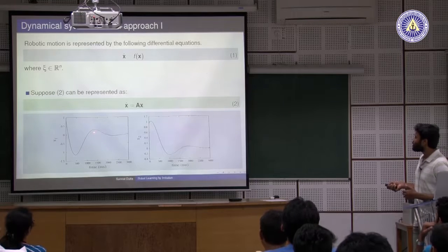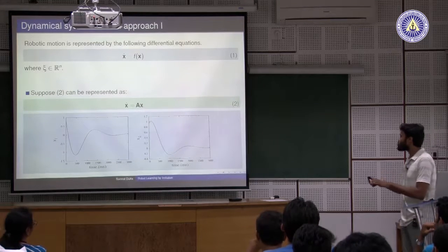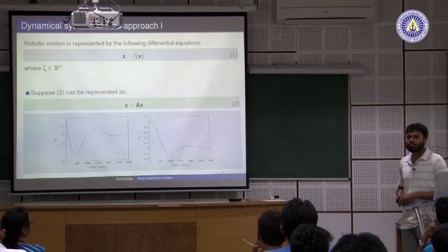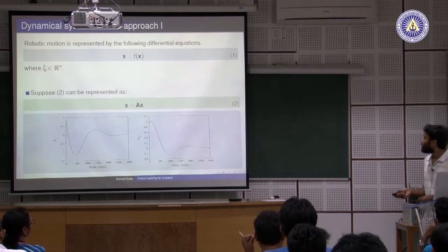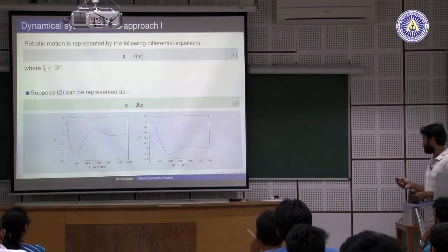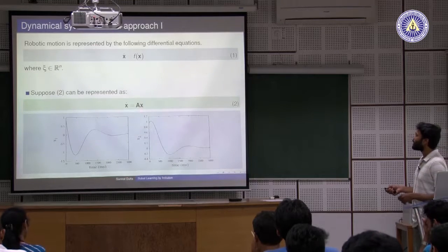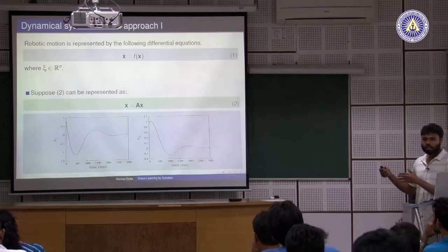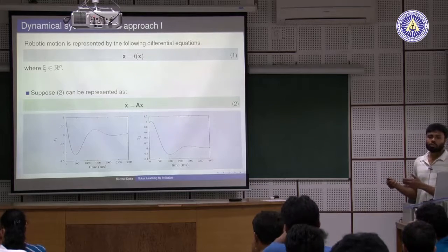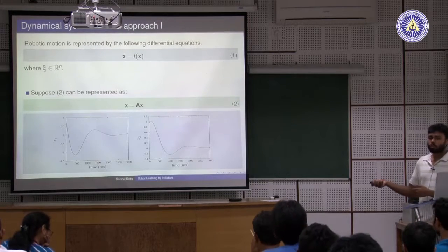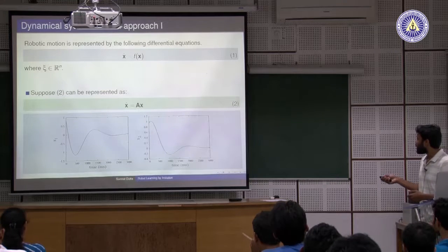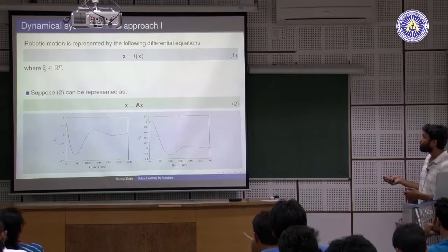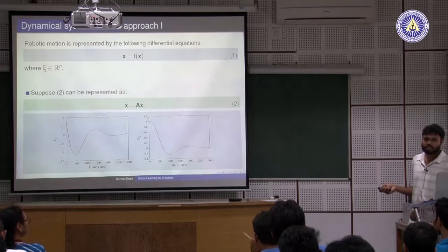Now, suppose this represents, in 1D, the motion of the end effector of the robot, how the end effector is moving in the workspace. If we say this is our motion planner, at each instant we get the commanded velocity, the position at the next instant is calculated from that velocity, and we tell the robot to go to that position, right. That is how it goes. So, for each particular set of A we will have a different kind of trajectory, right.